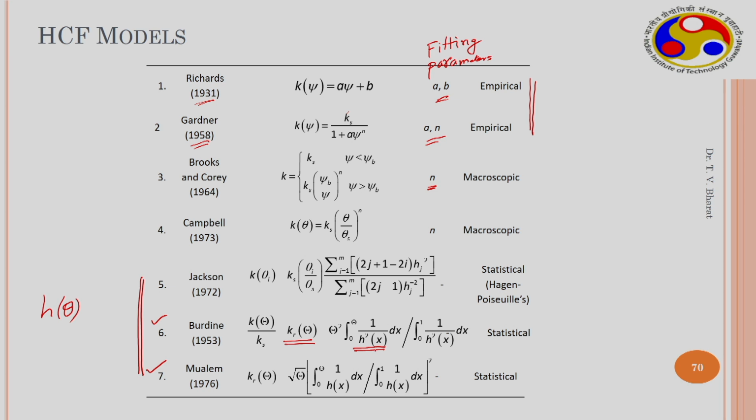This is also seen for many coarse grained soils. These models provide very satisfactory results. Here if you see the van Genuchten model, if you recollect, theta is equal to 1 by 1 plus alpha h power n, and whole power m. So here it is written theta equals a function of h, but this also can be written as h as another function of theta. So inverse is very easy to do, because that is what is required for the estimation of hydraulic conductivity functions